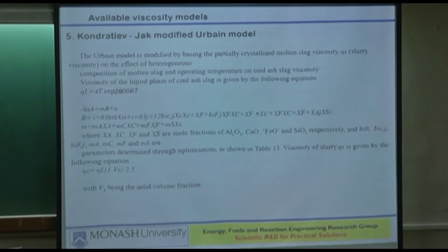So, as opposed to just the amorphous nature, slags can be partially crystalline as well, but they will still be flowing. And whether they will flow to the extent that the gasifier manufacturers want, that's a different story. Their viscosity may not lie completely within the range specified by the gasifier manufacturers.